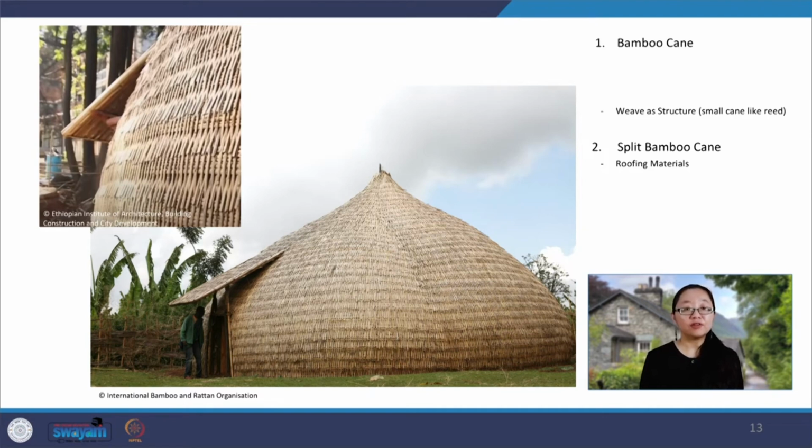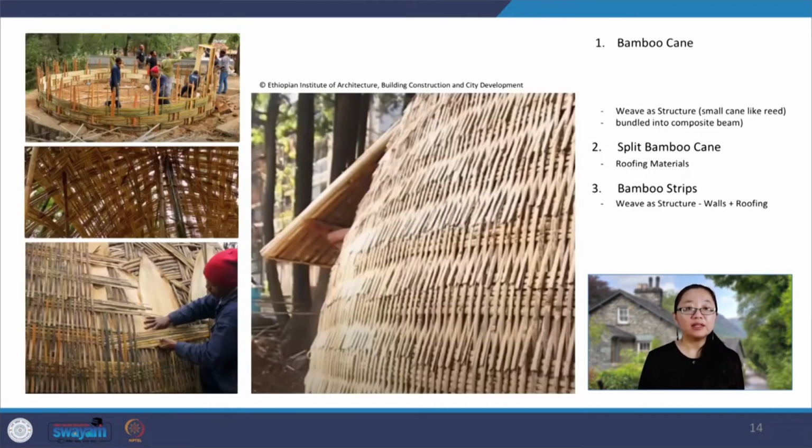The construction of the house begins with juniper tree poles which are arranged in circular as a component for foundation, because of its longevity and being proven to protect against pests like termites. Thin bamboo are placed around the perimeter of the house. It can be placed up to 100 to 150 centimeters underground.